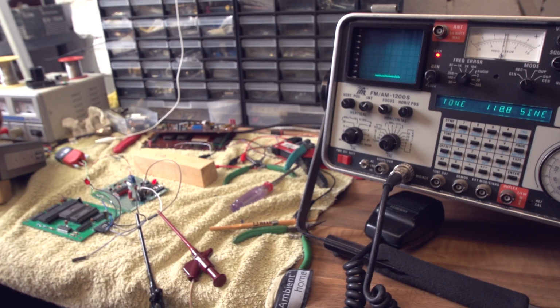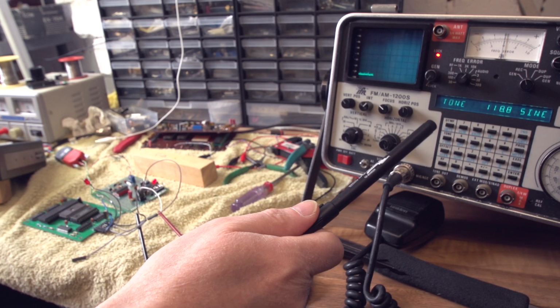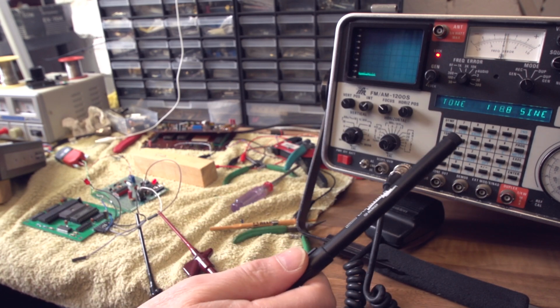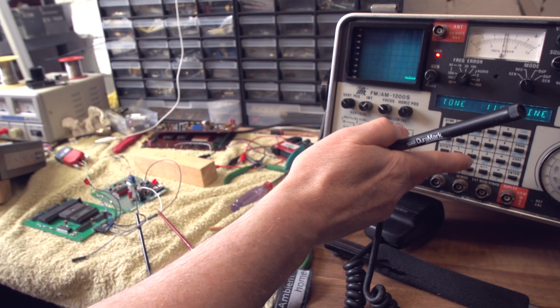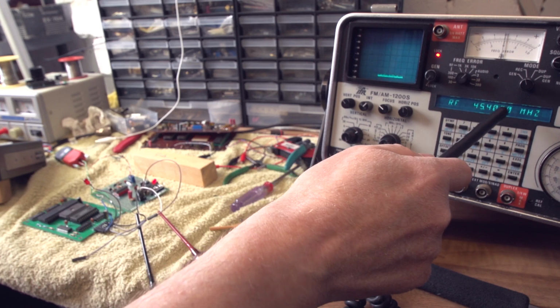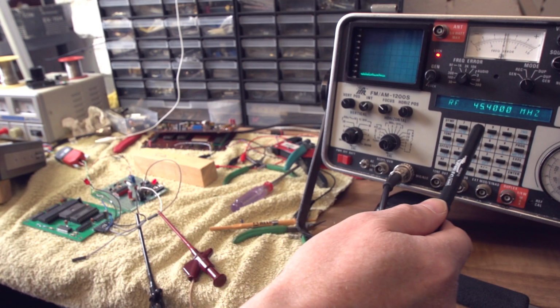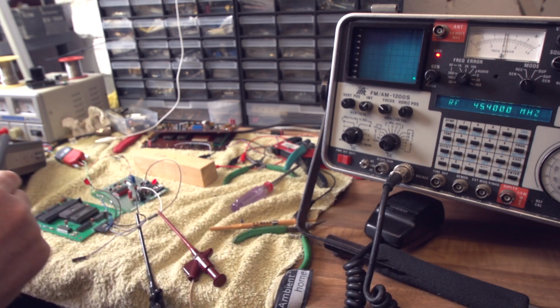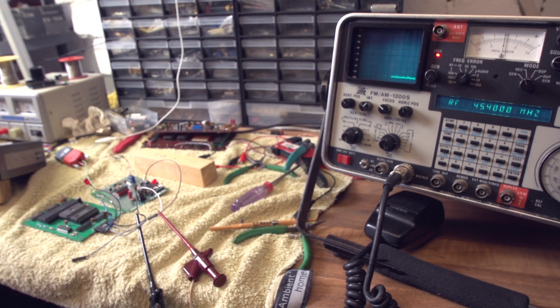Yeah, so I'm using the IFR again, and we're generating an output. This time we are using it as an RF generator as well as an AF generator. So our RF frequency I've got set to 145.4 megahertz, 145.400, and that's going to be transmitting through to the radio, which then sends the signals to the repeater card. So I just need to adjust the radio to 400.